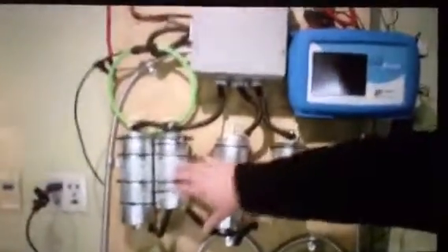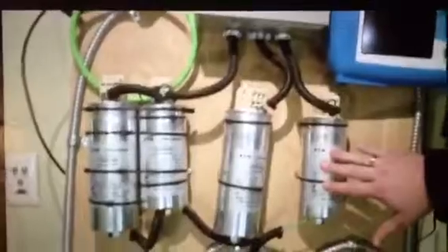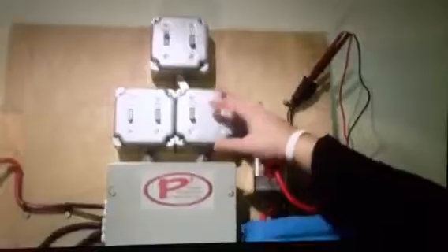Now up here on this board, what we have here is two inductive motors, similar to what you might see in an industrial application. And above those on this board are different capacitors of different kVAR values, also tied to switches that we can manually operate through this live demonstration. And then over here to the right, what we have is a power quality meter that can measure and document all of these kVAR, kVA, and kW demands. So now what I'd like to do is turn on one of these motors and show you what the actual power factor is.